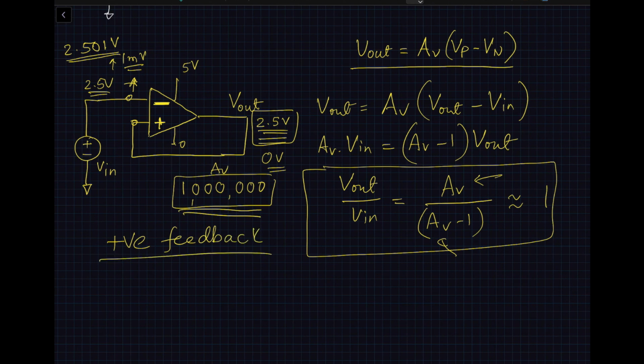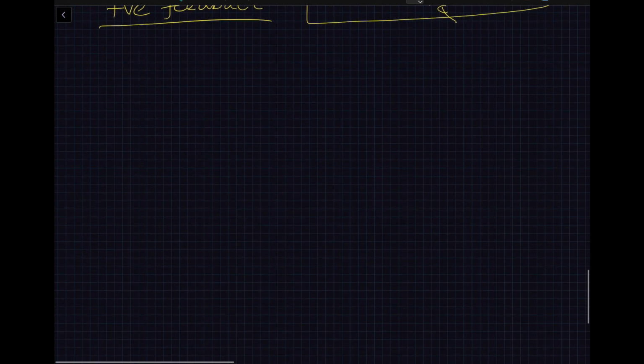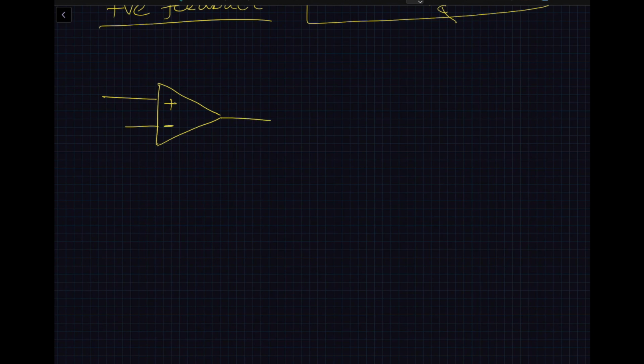Okay, so watch out for feedback before you start analyzing the circuits, because you may fool yourself. You may assume that the circuit will behave in a certain way, only to find out that the positive feedback will spoil the party. Okay, so to have a negative feedback, you would draw the circuit in this fashion. The classic example would be something like this. So you have positive input, negative input, and this is again V out, which we call positive output. So this we need to go over here. So we can see now we have a negative feedback in this particular loop.